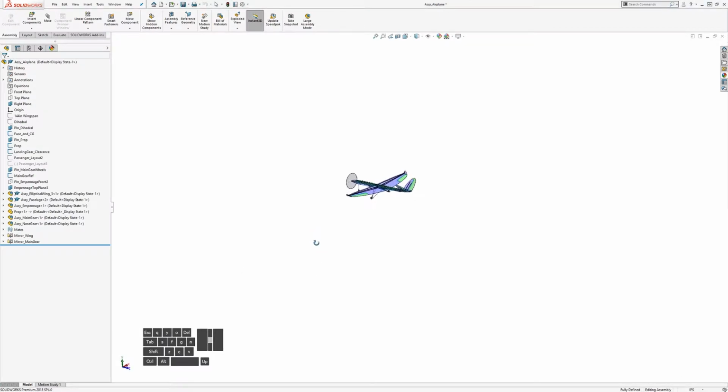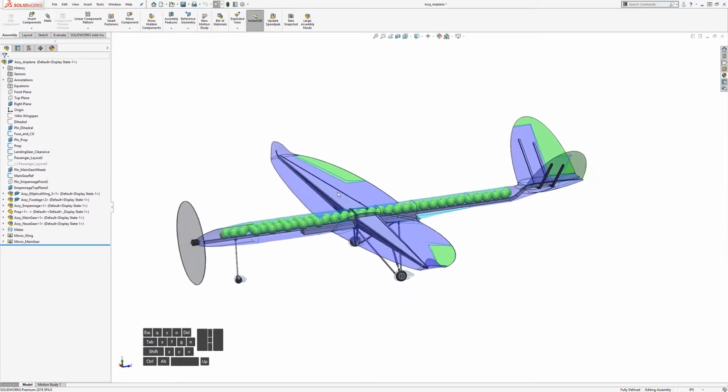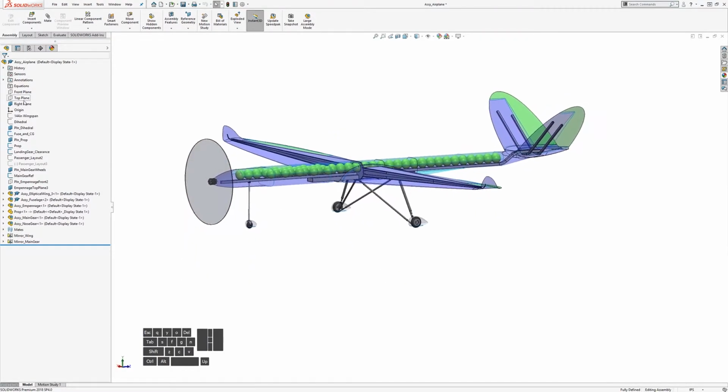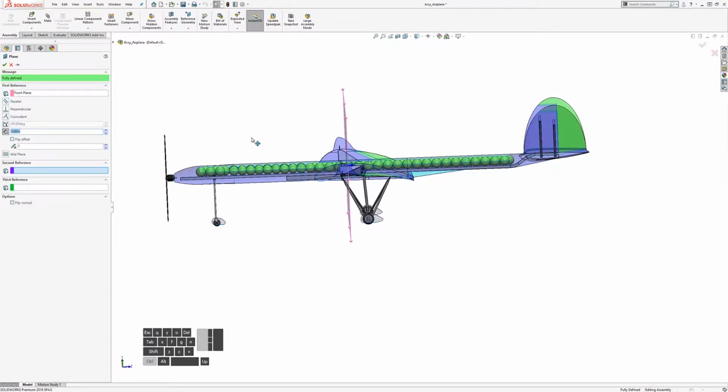Okay, so we're in just as a reference shape to have in there so that we can illustrate the difference between Coincident and Pierce. So let's take the front plane here, and just so it's not in the wing, let's move one up here and sketch in there.